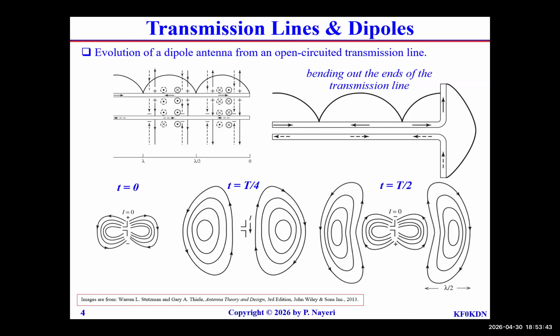And you said if the total from here to here is half a wavelength, that will cause waves to propagate. It creates these field lines. So what if this is 1/2 wavelength? This is quarter wavelength, right? And what happens in a transmission line? Remember the standing waves? The repetition period for a standing wave is what? If you have a regular line, it's lambda. If you have a transmission line that has standing waves, then it's lambda over 2. This is exactly why that occurs. Lambda over 2 is that period of standing wave. So that corresponds directly to how a dipole works.